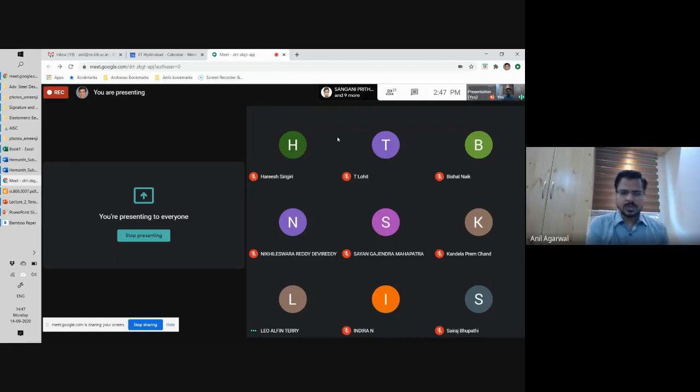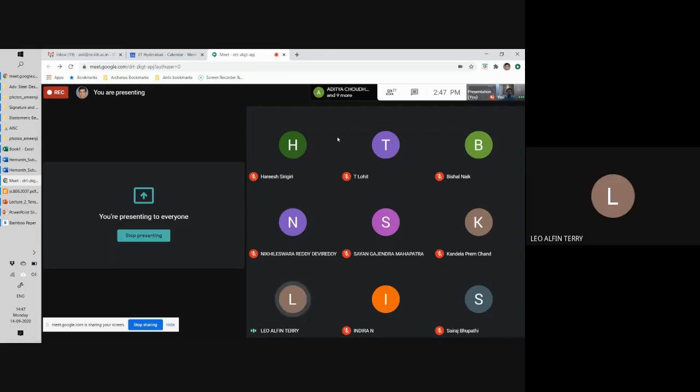So strength criteria, like strength limit state. Do you want to try again? Strength limit state means we are mainly reducing the strength parameters, underestimating the strength and overestimating the loads for design purposes, like that.